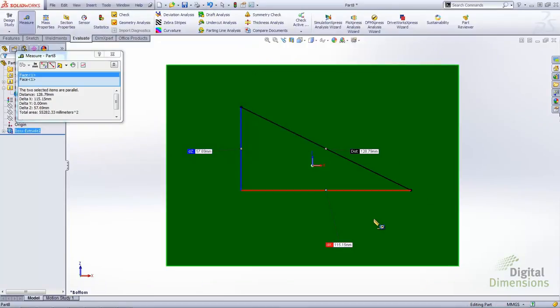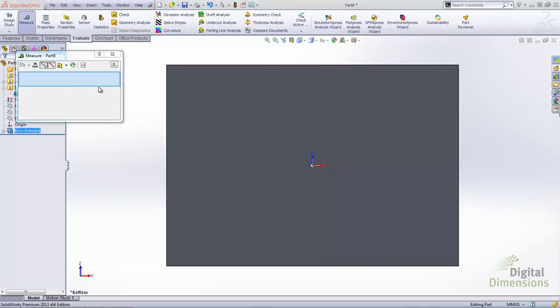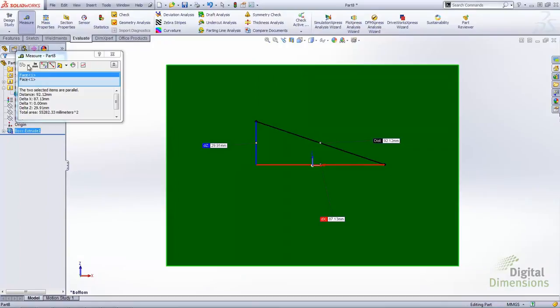Further revisions to the measurement tool has changed the icon for creating the sensor. It is no longer the floppy disk icon. You now see the updated graph icon. Additionally, you have the ability to measure between multiple arcs. Arc measurements can be customized to measure from center to center, min to max, max to min, or any combination thereabove. The last and perhaps most important change to the measure tool is the measurement history.